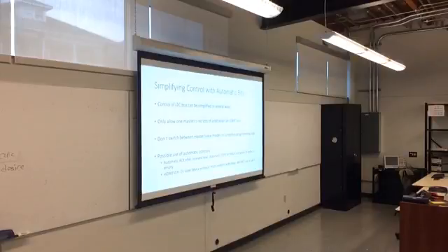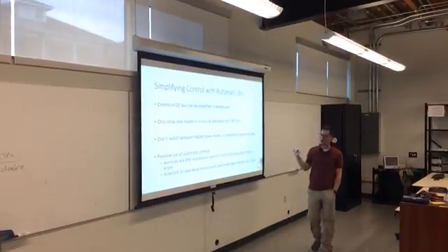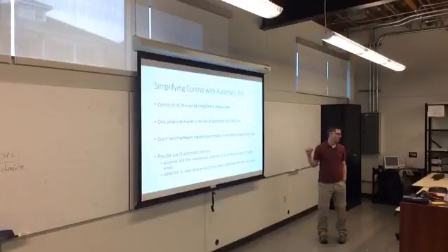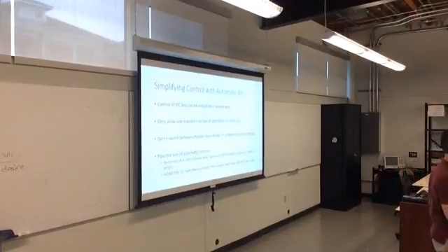It's the same as when we were talking to the accelerometer over SPI, where there was the automatic chip select line. I said don't use it because you'd like to have explicit control over that line. The same argument applies here. You should probably send your own start and stop bits instead of trusting that the hardware is going to do it for you at the right time.